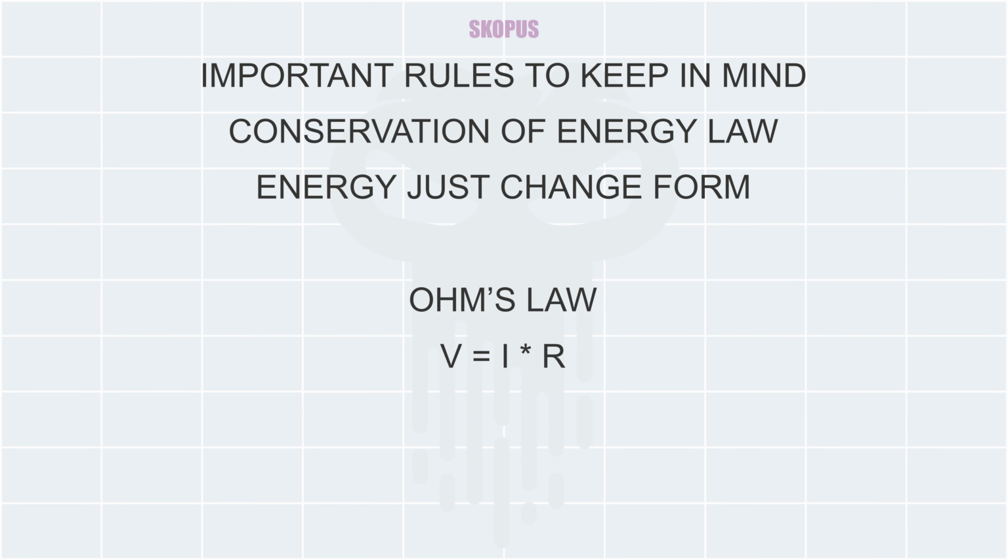What is it saying? It basically says that voltage is equal to the amount of current multiplied by resistance. For example, if we go back to our DC power source with the resistor, consider a voltage for the power source and a resistance for the resistor. We can put it in this formula and see how much current is going to pass through our circuit.